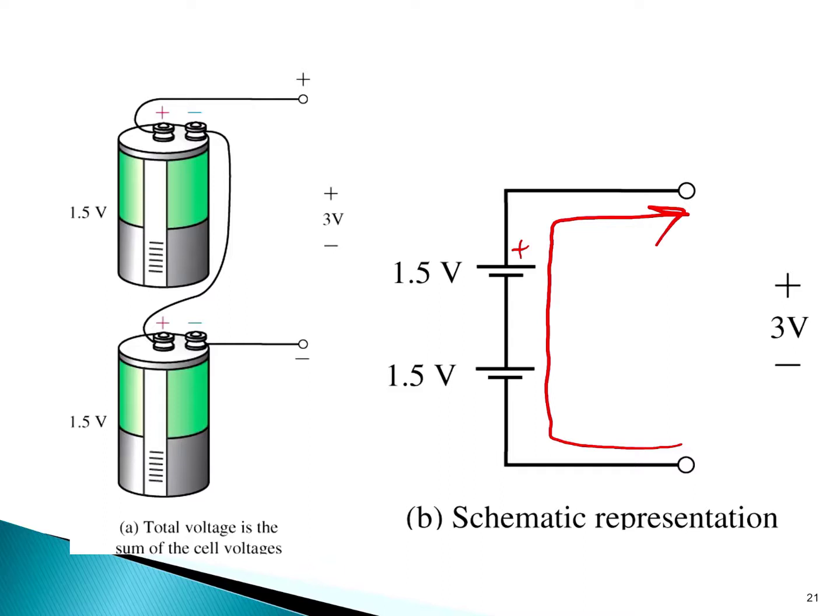So when we look at the current that would be conducted by these batteries when a load is connected, you can see there is one path for current to flow and a connection that is positive to negative. If there were more in series, positive to negative, what we have is additive voltage. The pressure is increased from a single battery to that of 2 batteries, to that of 3 batteries, to that of 4 batteries.